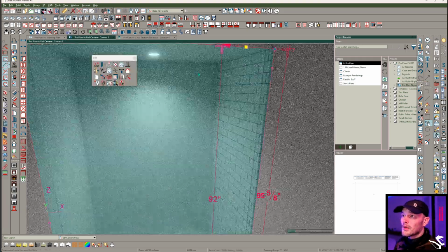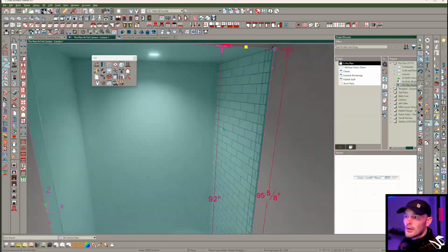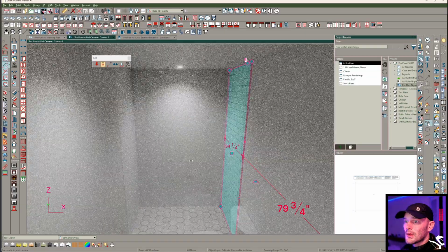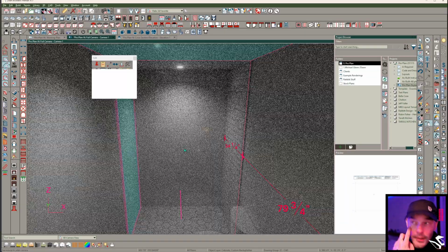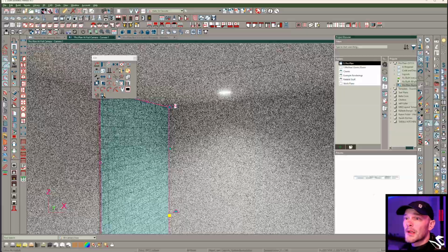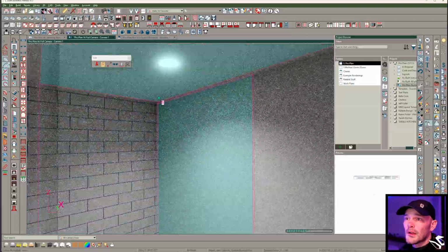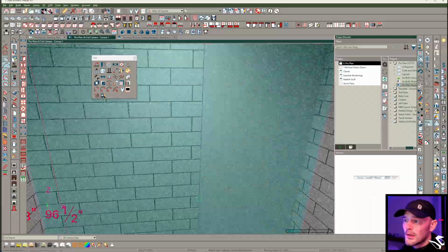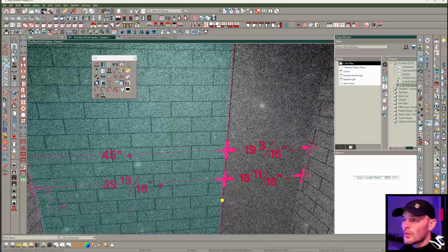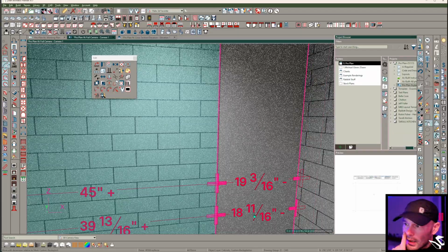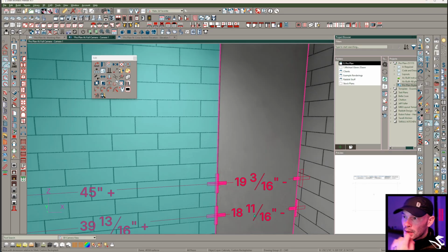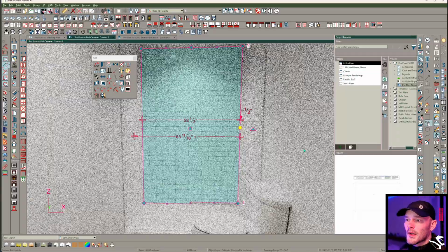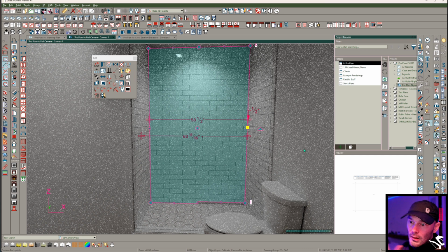Not bad. Now, if I try to select this, I've got a wall in the way. So I've got to navigate onto the interior side of this to be able to copy paste this, reflect about the center, get it on the other side, and maybe copy paste and reflect about the diagonal to get it on this back wall, right? And so this is not the worst workflow. This works, I can click on this dimension string and say 0 inch to just push that backsplash all the way to the side. And there we go. We've got the makings of what might look like a shower.